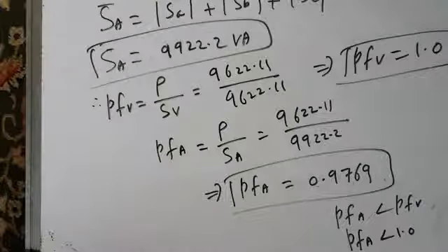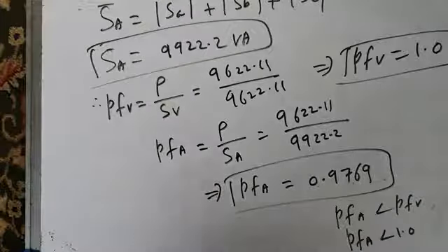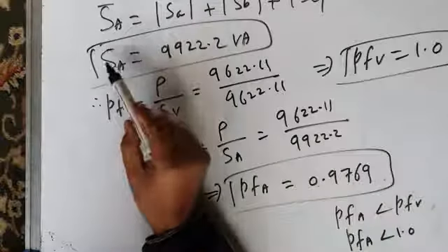Why is it so? We have to go back to the earlier lectures when we were discussing three-phase unbalanced systems. In a three-phase unbalanced system, the line losses are very large as compared to the line or feeder losses of a balanced three-phase system. To take those line losses into consideration, we define another type of apparent power.